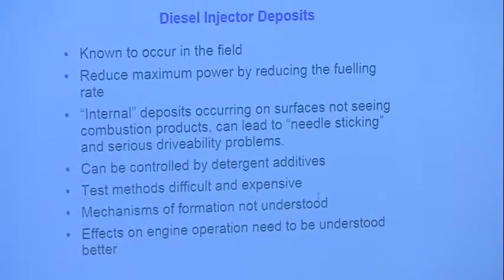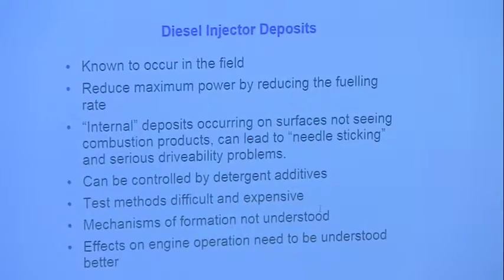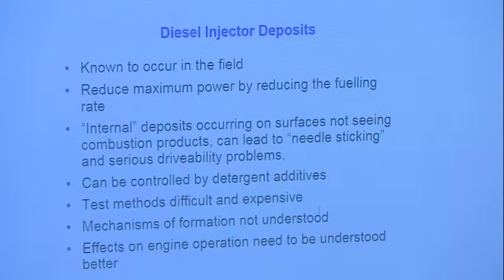So what you do in this test is basically run for, I think it's 80 hours or 100 hours, I don't remember now. But the maximum power will come down in these tests. And that is the measure. That's how you measure deposit formation. And then if you put a detergent additive in the fuel, that doesn't happen, basically. And that's how you rate how effective the detergent additive is.